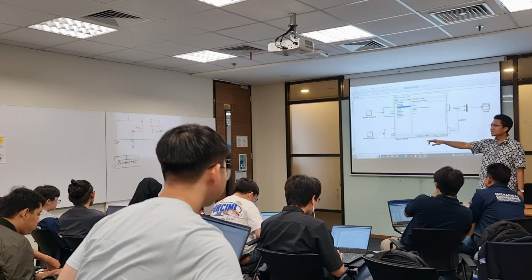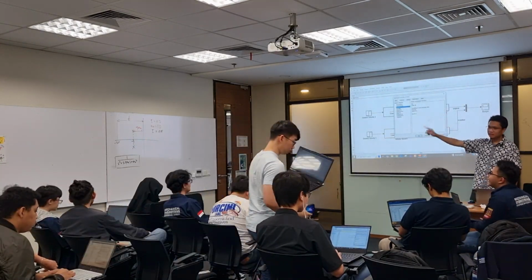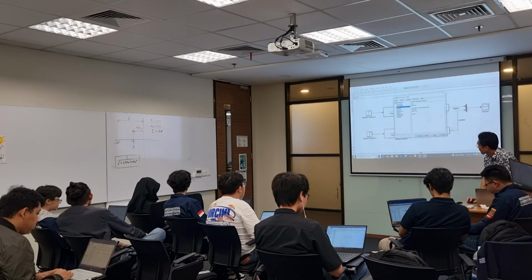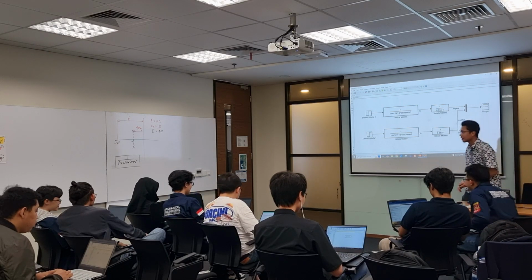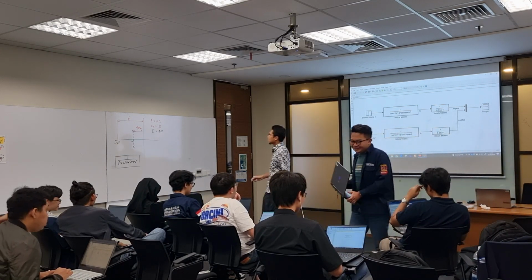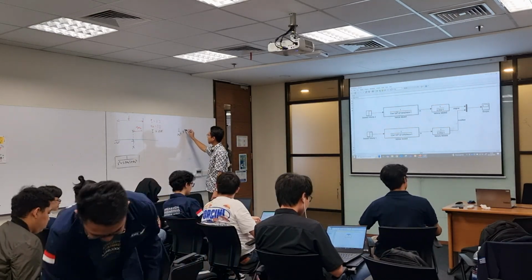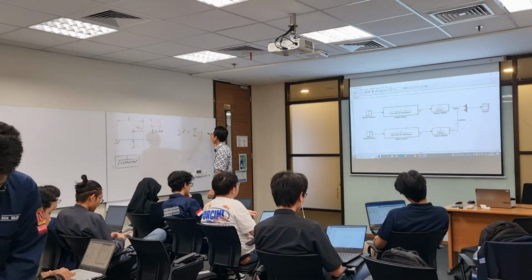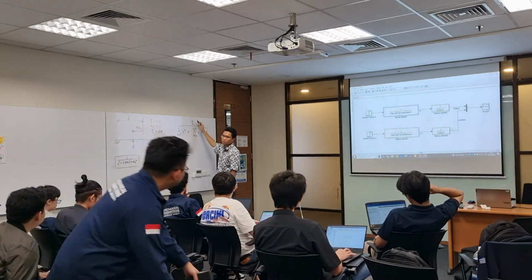You have the omega n, you have the zeta, right? So you just compute all of them, 1 over omega n squared. So you put 1 over omega n squared, s squared, and here is 2 zeta, plus 1. So this will be your transfer function.